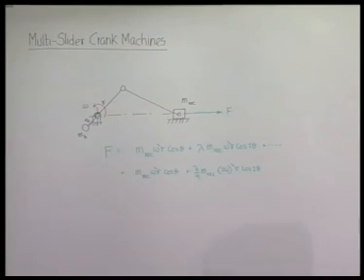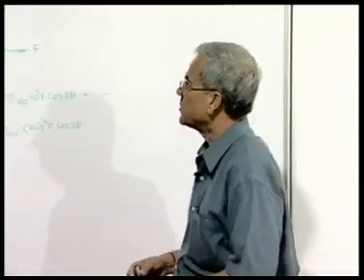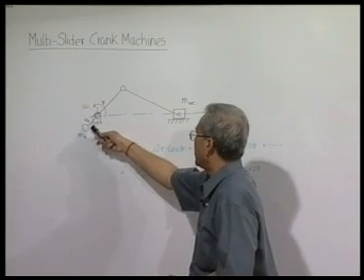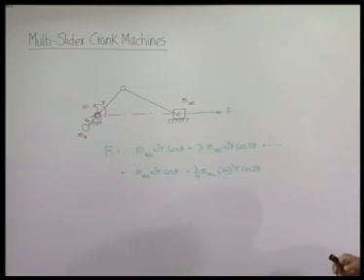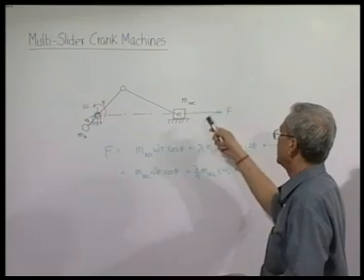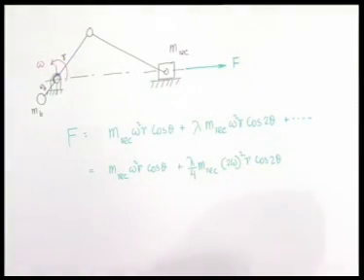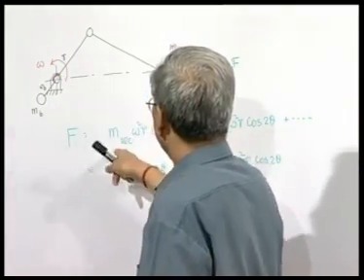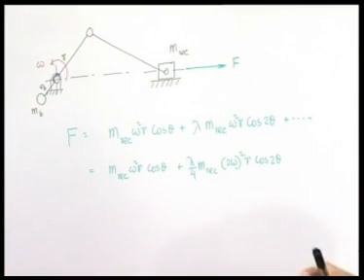In the last session, we have seen that a machine or an engine consisting of a single slider crank mechanism produces unbalanced forces, a part of which can be balanced by placing a balancing mass as a counterweight to the crank, and the reciprocating mass produces an unbalanced oscillating force along the system center line, and it can be expressed in terms of an infinite series of harmonic quantities.